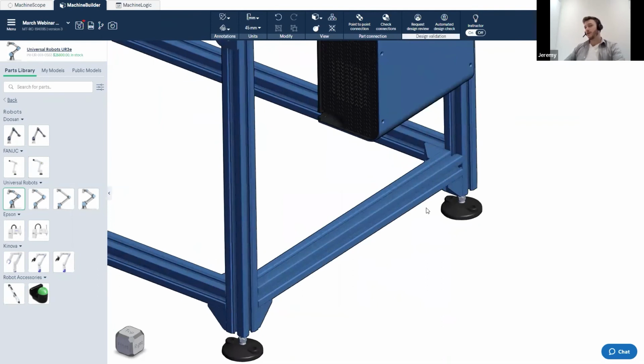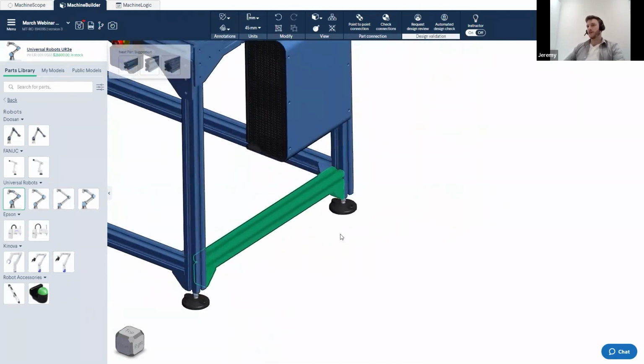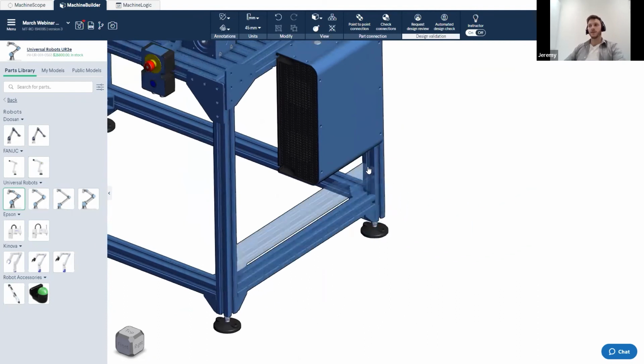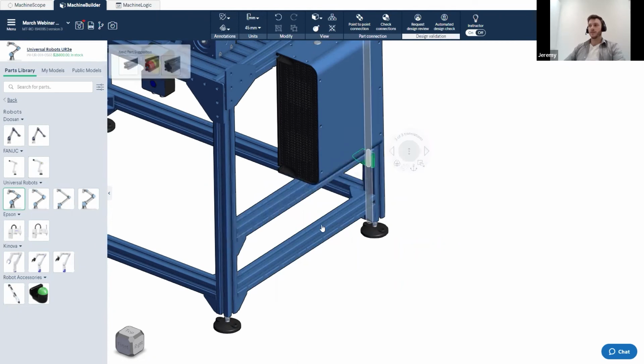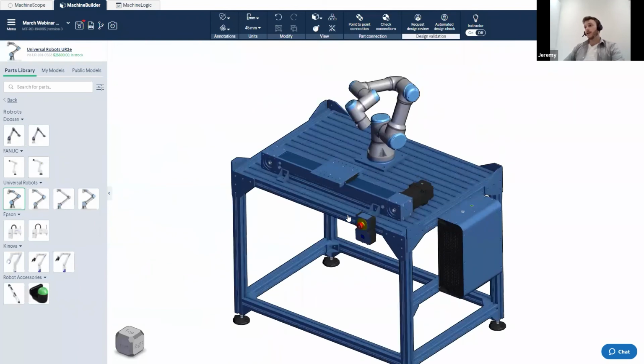To highlight them, I can use drag and drop, but if you'd like to select a bit more precisely, if you hold Control, you can then select individual items one at a time. If you select an extra part that you don't need, click it again to unselect it. From here, you can press Control-C, similar to any other software, such as Microsoft Word, Google Chrome, etc., and Control-V to paste it again. In this case, since it's a lot less fine-tuned designing, I can simply drag it to the general location I like to attach it to, press Enter, and then slide it up to its appropriate location.